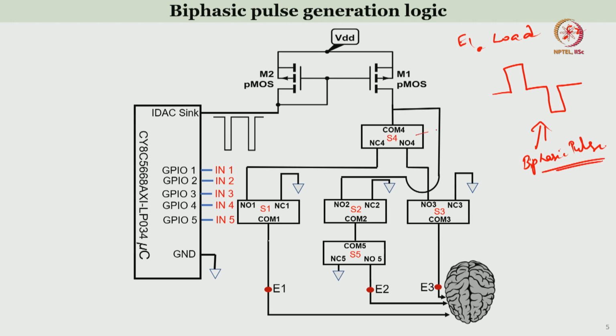So, these are the switches, SPDT switches, single pole double throw switches. You can think of them as a 2x1 multiplexer or something like that. You have two outputs, and there is a pole. This is output 1, output 2. In switch terminology they say NC, normally closed, normally open, COM, something like that.